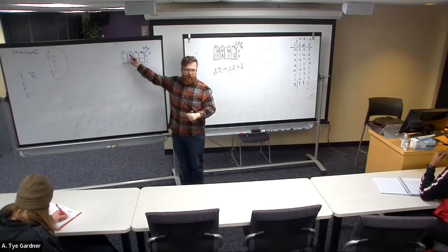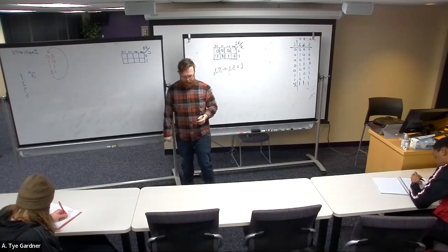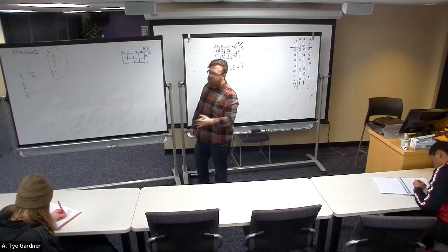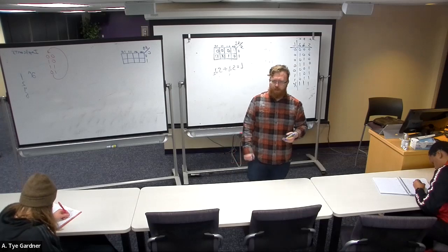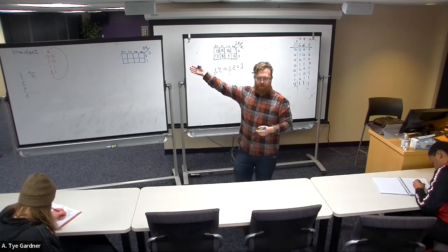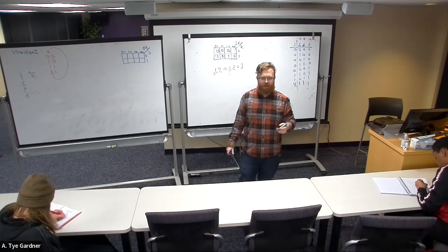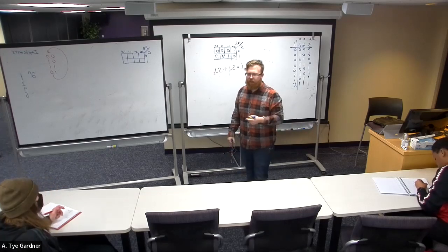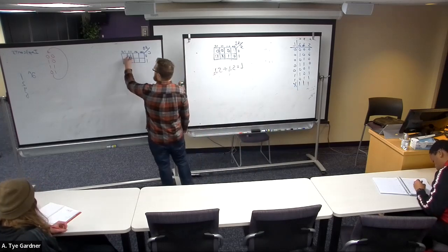Don't forget this. I'm going to repeat it. Don't forget to gray code it, because you'll get it wrong. Oftentimes, especially on exams and sometimes on homeworks, if I'm really good, I will provide you with the K-map because I want you to have specific ordered variables so that everybody's answers end up the same, because K-maps are really hard to grade. That's all.